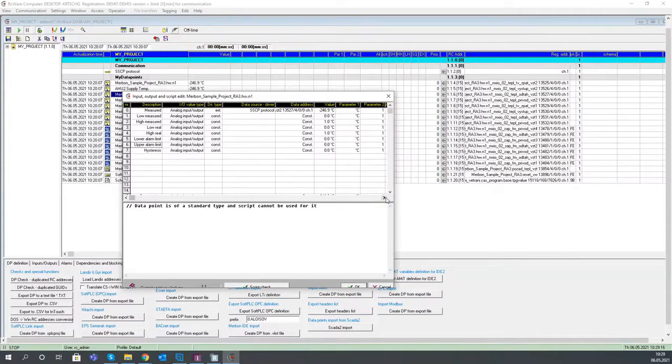Normally this is not done. You can do it if you want to monitor an alarm directly in SCADA. But in building controls, we mostly use alarms which are initiated down in the PLCs and have a multi-state form, like they can be acknowledged, reset, and so on. So this is just maybe to enhance the possibilities of the SCADA.